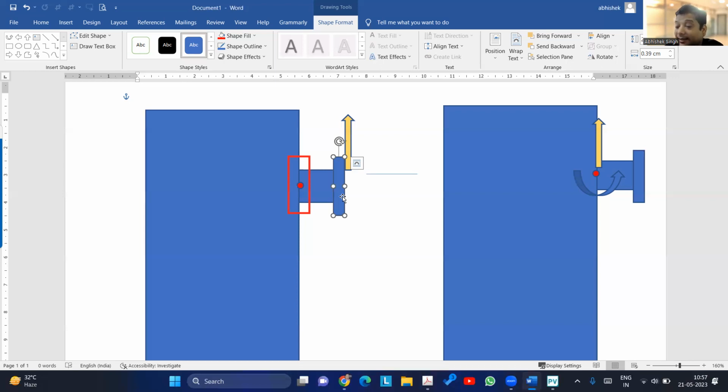Okay. Now in our case, there is extra loading coming. So can I say that it will still be able to take the same pressure and temperature? No, right, Akash? So definitely we don't know how much strength has reduced, but we feel that, because apart from pressure and temperature there are other loads present, the pressure-taking capability of this flange may have reduced. Can I conclude that? Is everybody getting that? Can I say that?